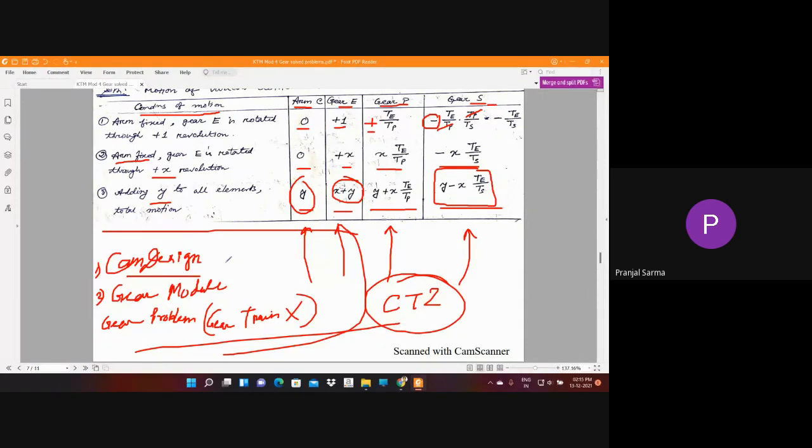What are the stages involved in cam profile construction? All those things should be written properly, all those assumptions, the scale, whatever you have considered. First of all, write the given data, the scheme of motion for different strokes, suppose ascent stroke, descent stroke, etc. And as per that, by considering a proper scale, you need to draw the displacement diagram. After that, write about the assumption that you consider, that is the kinematic inversion. Let's consider the cam is stationary and the follower is rotating around the cam in which direction, etc. Also write what value of r you have considered for drawing the circle.